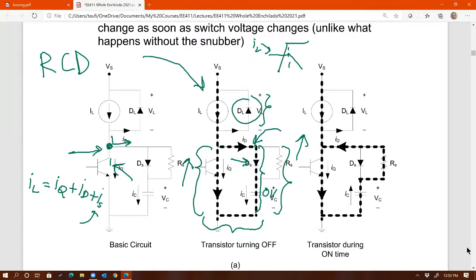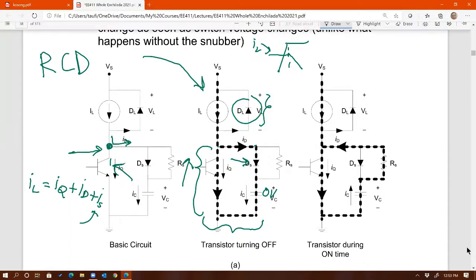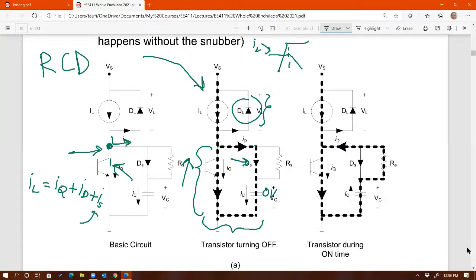As the switch voltage goes up to 1 volt, for example, this is going to be increasing as well to 1 volt. But this capacitor is going to be slowly charging because this is forward biased. So by gradually increasing the switch voltage, you are forward biasing the diode, and in the process, you are charging the capacitor right there.